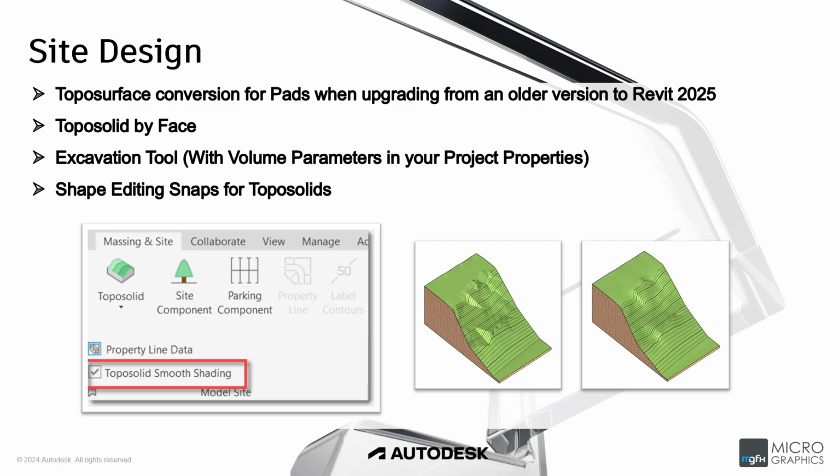The Excavation tool offers volume parameters in your type properties, in your project properties on the side, and they're automatically created. Under shape editing and under the model site itself, you can also change the topo solid to have smooth shading, not having all those convex lines and indents, making it more seamless and better for presentation.